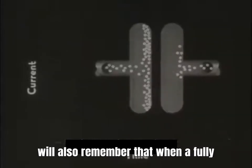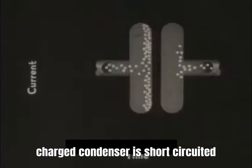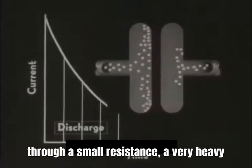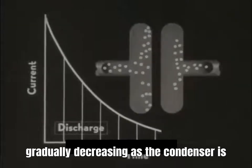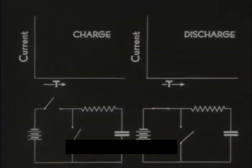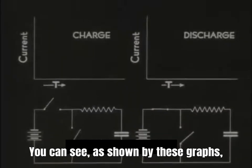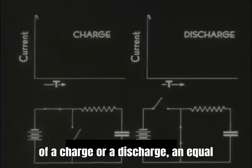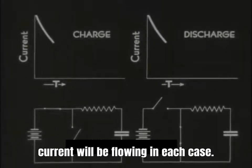You will also remember that when a fully charged condenser is short-circuited through a small resistance, a very heavy current flows immediately, the amount gradually decreasing as the condenser is drained of its charge. You can see, as shown by these graphs, that at a given time after the beginning of a charge or a discharge, an equal current will be flowing in each case.